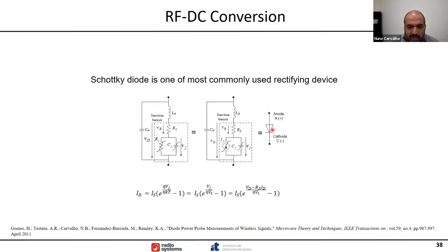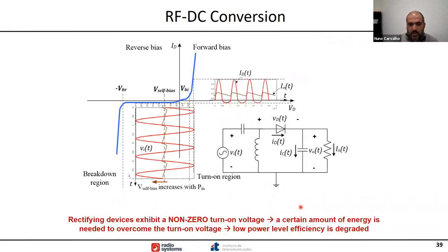And if you look inside, the diode is a complex structure. It normally has some parasitics and a nonlinear current. You can represent it by a nonlinear resistor and a nonlinear capacitor. And as you know, the equivalent model of the diode is normally given by the Shockley equation, where you have your saturation current and your thermal voltage VT and so on. So this is really the operation of your diode: mainly an exponential function with a breakdown. If you increase the negative voltage a lot, you'll get to a breakdown situation.